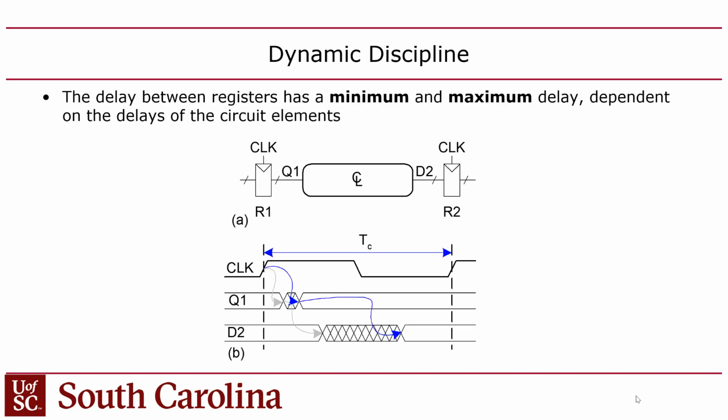Okay, so let's go into a little bit more detail here. If you have a synchronous design, for example, the pipeline or finite state machine type designs that we looked at in the last lecture, they have a bunch of paths that begin with a register and end with a register, or flip-flop, right? Within each clock cycle, that blob of logic between these two registers is going to have a propagation delay and a contamination delay. And those have to include the impact of the registers too.